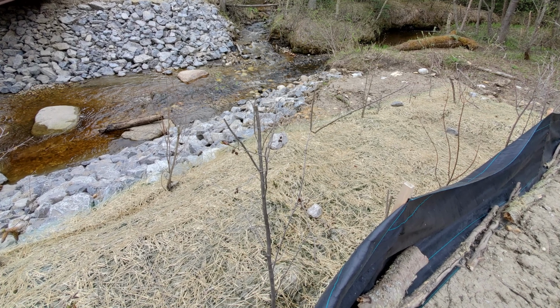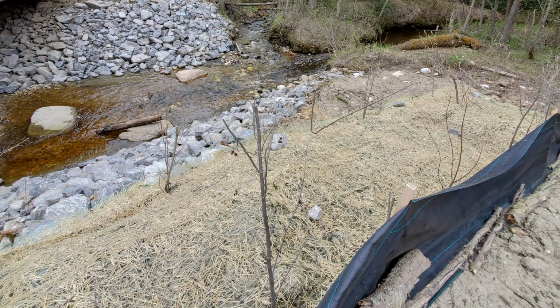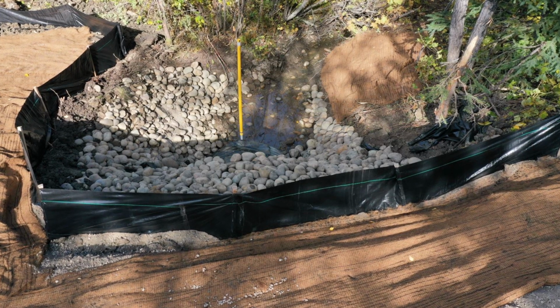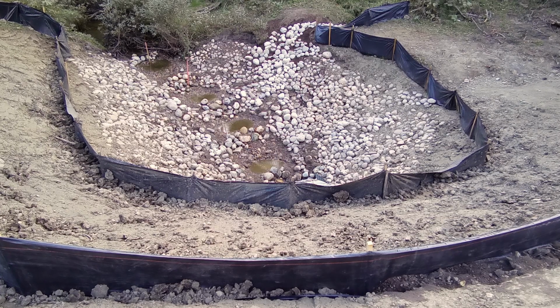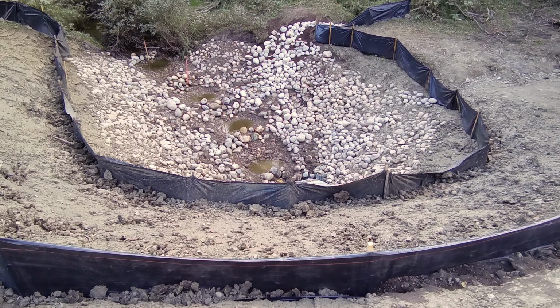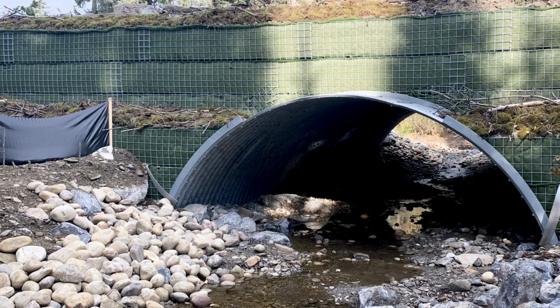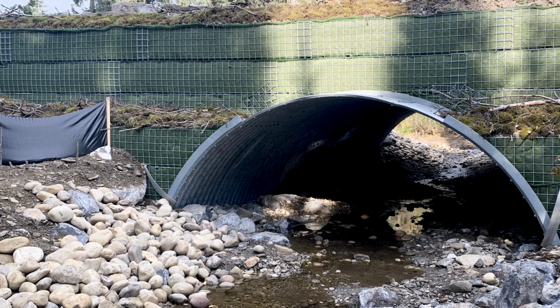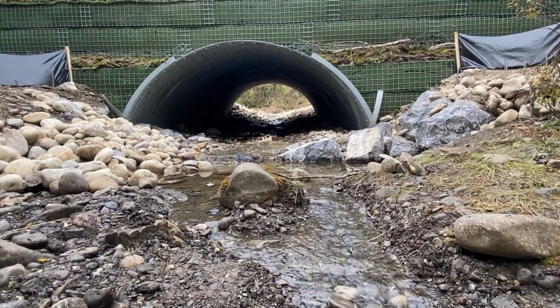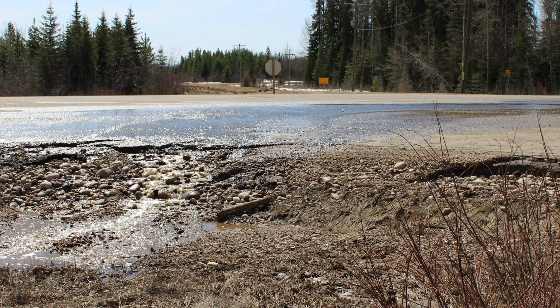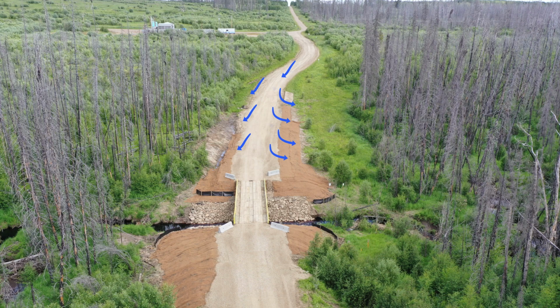Erosion control is a standard aspect of any crossing design. Designers will specify standard erosion control measures plus additional site-specific measures based on the expected water velocity during a design flow flood event. It is important to include erosion and sediment control measures at both the inlet and outlet of the watercourse crossing structure. Design should always include consideration of runoff and erosion from roads. Road drainage should be directed away from the structure to prevent sediment from entering the watercourse.